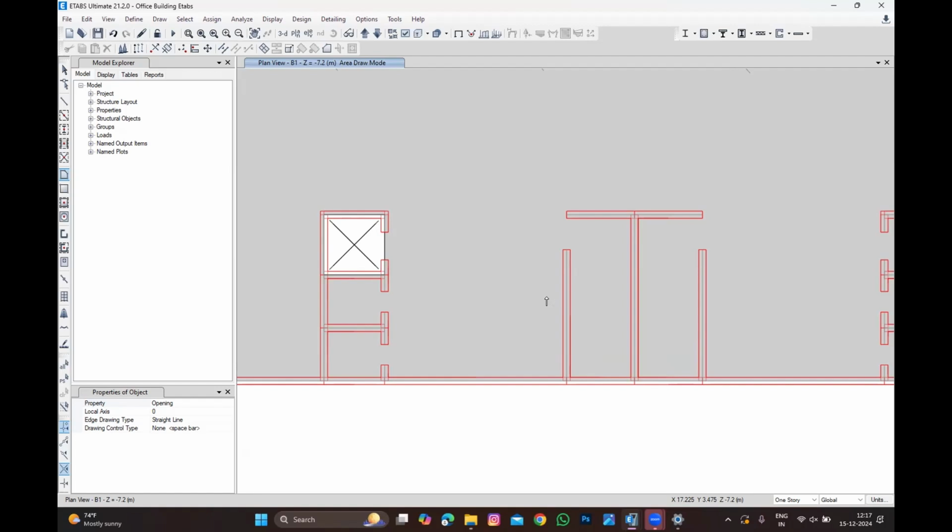The waist slab, though you are going to cast, I do understand. Waist slab you are not going to cast at the beginning. You are going to cast in a very later stage, or even when the structure has gone one-third or two-thirds, you will go for waist slabs. I completely agree because the core in a high-rise building will go first, then the slabs, right? Actually, the core will go even 5 floors above the slabs because of your jumping formwork system, the core wall will go above.